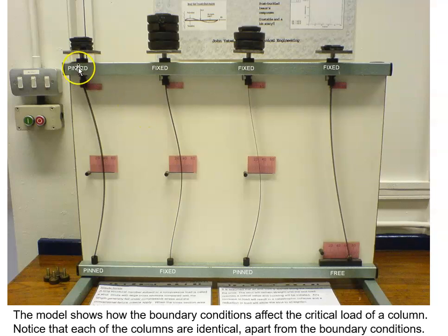Kind of different from the chart before, this one shows us, with weight, that while accomplishing the same amount of deflection, the fixed-fixed column carries a lot more load than the others. Fixed and pinned carries the second greatest amount of load, and pinned the third greatest, all with the same amount of deflection. And fixed-free comes in 4th place, and we can see just how far that moved. It moved a lot more than those. It deflected a far greater amount than these three, with the least amount of load.